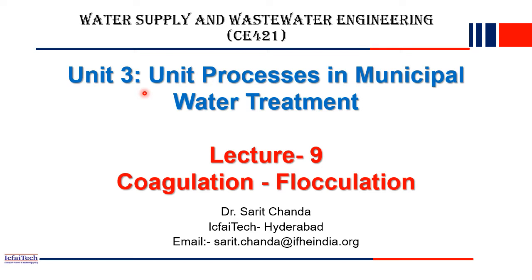So the first step is we provide the screen. The basic purpose of the screen is to filter out the floating objects present in the water. Once that is cleaned up, the next step is aeration. We have seen in the earlier lectures that aeration is a process where we are removing the toxic gases present in the water, as well as adding as much oxygen as possible from air to the water.